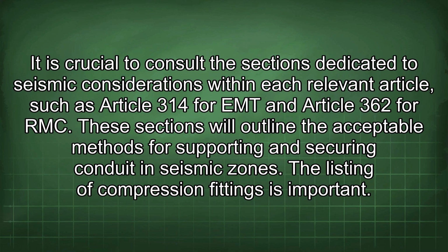It is crucial to consult the sections dedicated to seismic considerations within each relevant article, such as Article 314 for EMT and Article 362 for RMC. These sections will outline the acceptable methods for supporting and securing conduit in seismic zones.